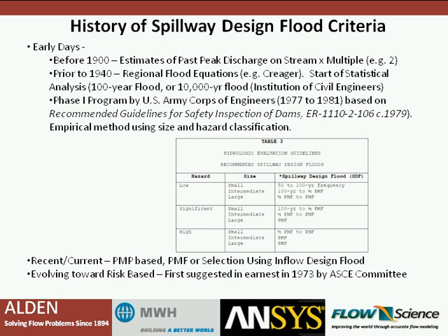Briefly here, I'll talk about the methodology that's been used to decide what flood we should be designing for. This is something that has changed in the past and actually may continue to evolve into the future. Originally, back in the early days, many of these projects that exist have been designed based on the largest flood that has been seen up to date. People figured that they would design for the largest flood that's occurred and maybe even double that, and that they shouldn't ever get a project flood larger than that one.